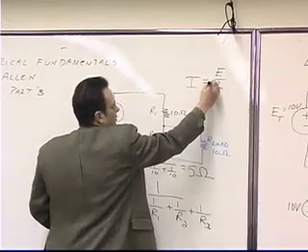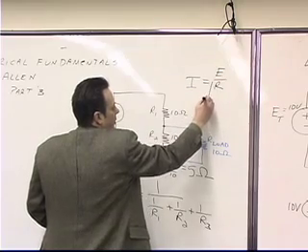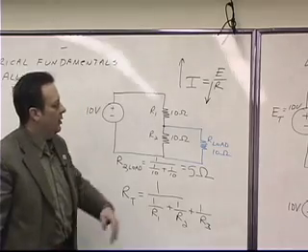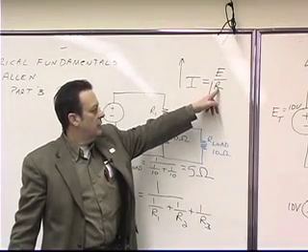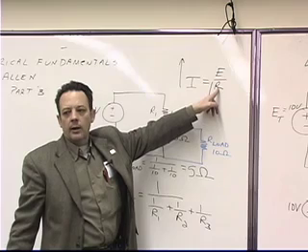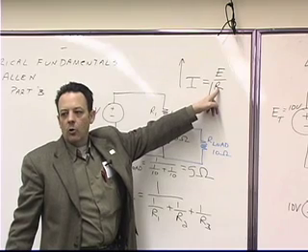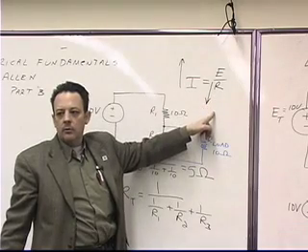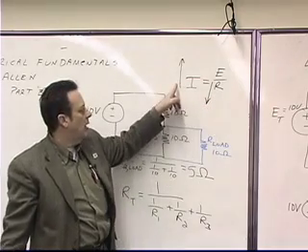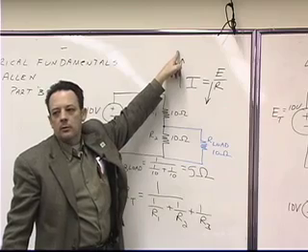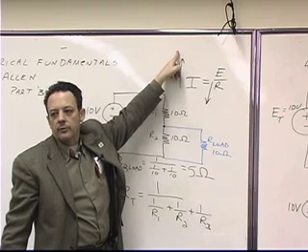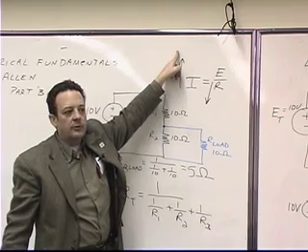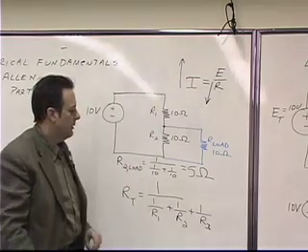So if the resistance goes down, the current goes up. In parallel circuits, when you connect more and more hair dryers, the total resistance of the hair dryers goes down. That means it's drawing more and more current from your circuit breaker panels. And that's why it's said that the load is increasing.